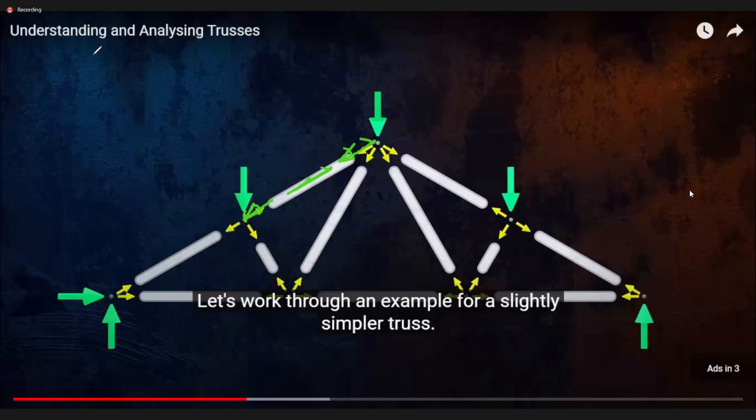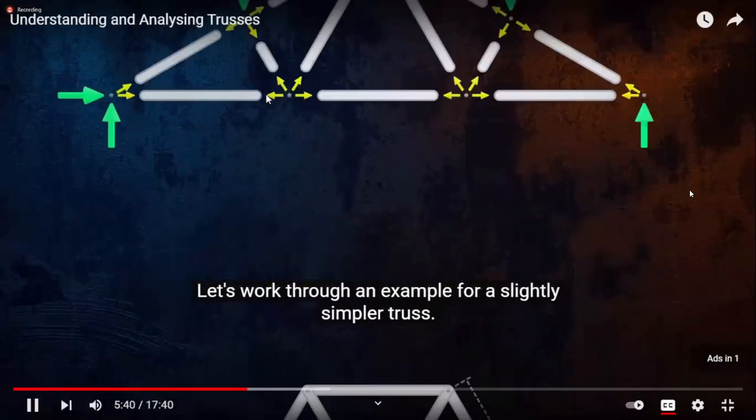Okay, so this is in tension, so it is giving a radially outward force on the joint. This is in tension, so it is giving a radially outward force on the joint. Well, you can assume it to be in compression also. Now here, if you assume every part to be in tension, and when you find that this tension is negative, then we know that it is actually in compression. Simpler truss.